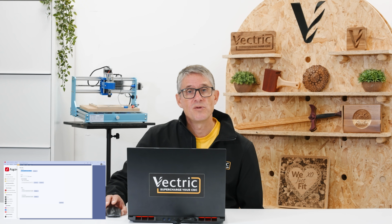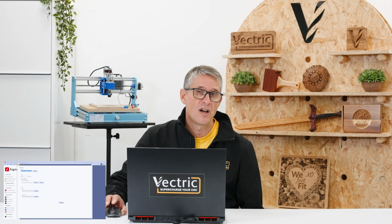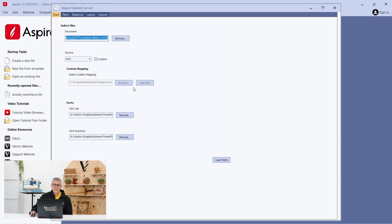So it's where you can also set up the spacing between parts, any border gaps that you want, and those features that are part of the nesting form typically. So with that template set up once, you're now good to go for all sorts of projects where you would realistically be using all the same settings. So I've set up one here, a template file. Like I say, this is a feature that's been in since 11, but we're using it now in a very effective way here.